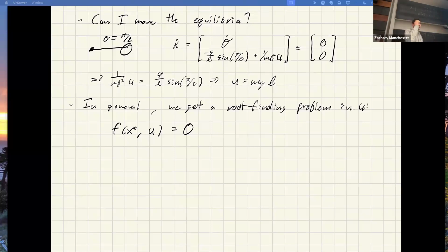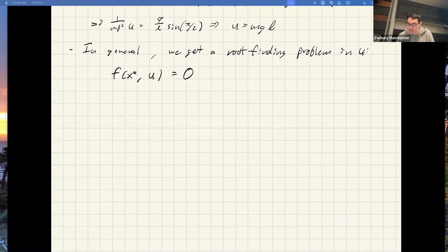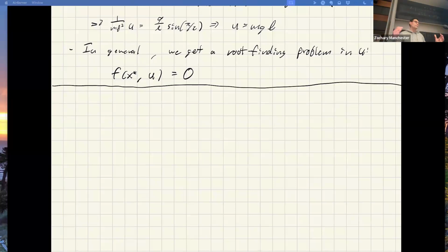That idea that I just said, where you have fewer actuators than joints or degrees of freedom, is called being underactuated. And that makes control harder and way more interesting. It means that we have to actually reason about the dynamics in a sophisticated way, and we can't just cancel stuff out arbitrarily. So yeah, this is a big topic. This idea of controllability comes up a lot. Okay, other thoughts, questions? Okay, cool. So next topic: now we know what an equilibrium point is. It's a place where the system will, if you put it there, stay there and not move anymore. Big idea. The next topic is stability of those equilibrium points.